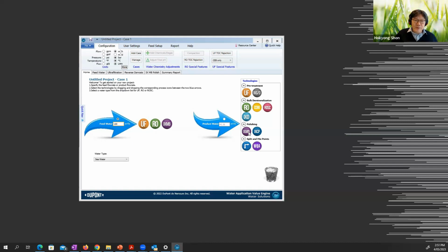So in this case, you can utilize the ion exchange resin to remove all the ions in your permeate water. Also, you have CCRO, closed circuit RO, which means when you have a very high recovery rate, you can just keep recirculating, and then you will have a very high concentration in the RO system. So when you utilize high recovery, closed circuit reverse osmosis can be used. But in your assignment, I don't think you even need an ion exchange membrane or resin.